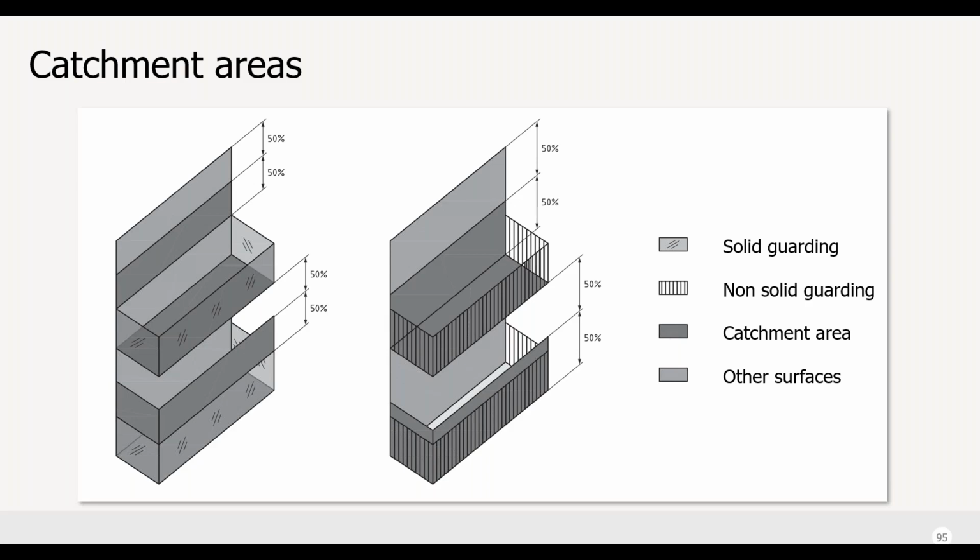It's important that the drain outlet is completely weatherproofed into it, and the overflow design, location, and discharge clearance are essential for the prevention of residual dripping.